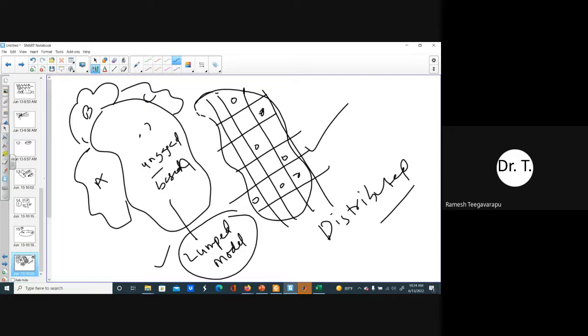The best you could do is come up with a single value of flood or a single value of rainfall in that area, and then apply it to the lumped model. So this can be more approximate values of your flood estimation. The distributed approach will be more accurate because you have both rain gauges as well as gridded precipitation data for ground truth checking, as well as bias corrections. I hope that answers the question.